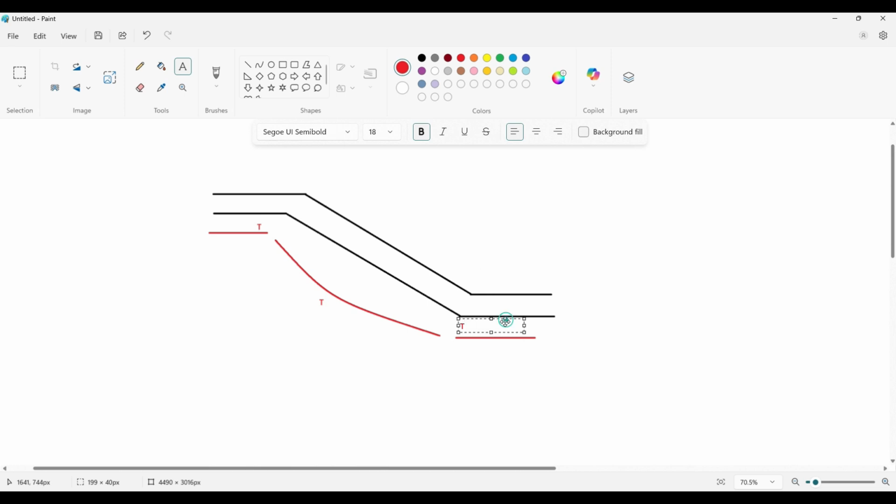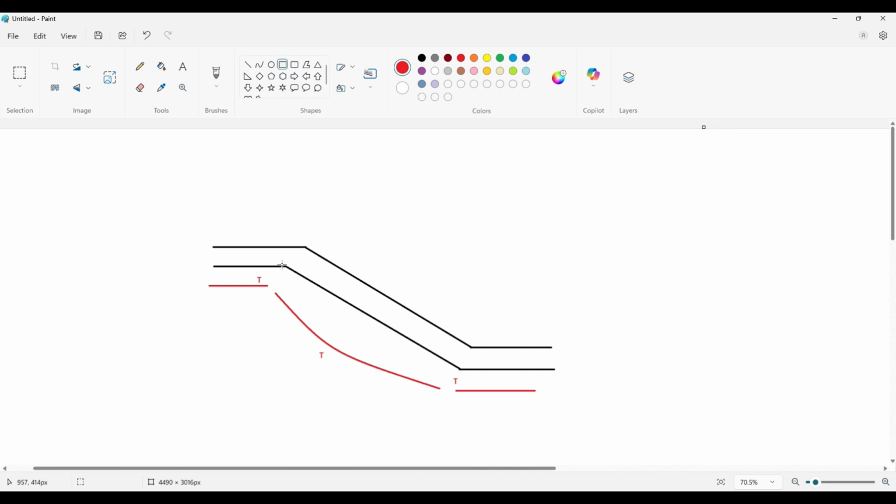Now I'm just showing it like this, but what really happens is, if for example I have a hidden beam somewhere over here, if you remember the last class, in our two-way slab when I was discussing the sunken slab, if you watch that video, in that video I have attached the site video of the staircase also. That was a slabless staircase, and I have shown you how that beam will actually be presented. So whenever the hidden beam or whatever beam is there, it is giving additional stiffness to your landing slab. Because of that additional stiffness, what ends up happening is you end up inducing tensions into your zone.